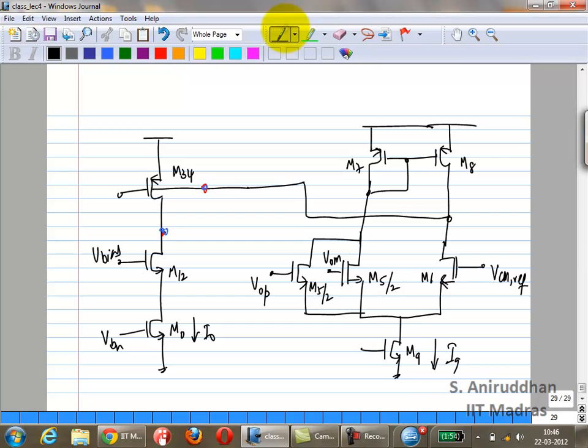Okay. Rest of the stuff remains the same, of course. So you still need this CC, right? This is your M34 and so on. So everything else remains the same. Now if you do this, you get GM5 VOP by 2 on one side, GM5 VON by 2 on the other side, and then you add the two. Okay?